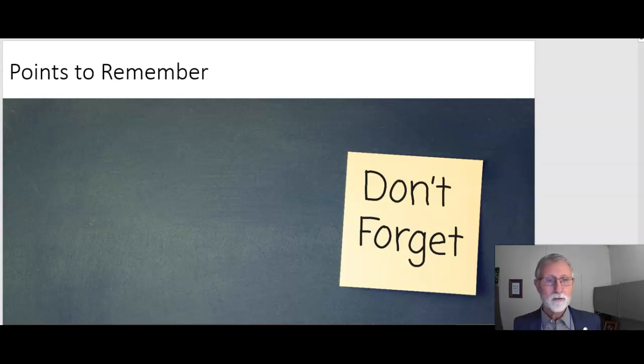When you choose something, you have to make sure that if it's especially an external, and you're trying to connect buildings, you choose the right antenna to get you the bandwidth and the data traffic you want. Now, you get different types of connectors based on the antenna type, and looking at the different connectors, you've got N types and TNC and SMA connectors. All of those are different, and is any one better than another? No, but some of them have different sizes. Just be careful.